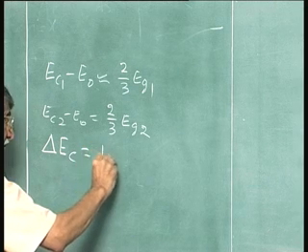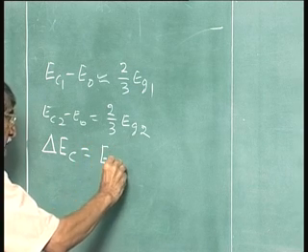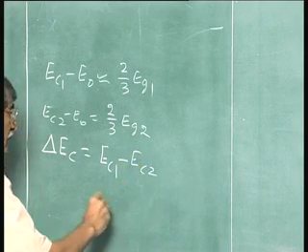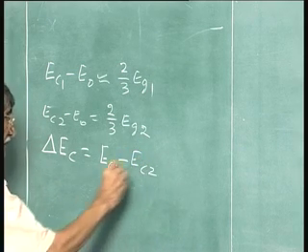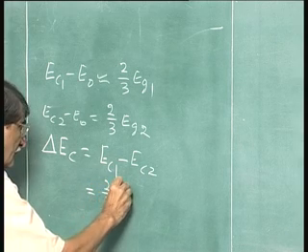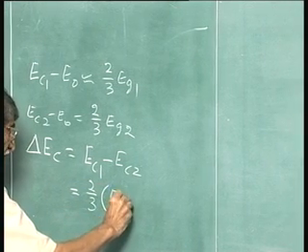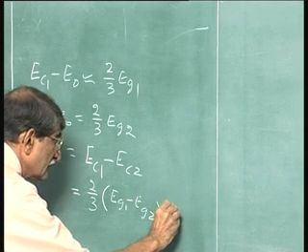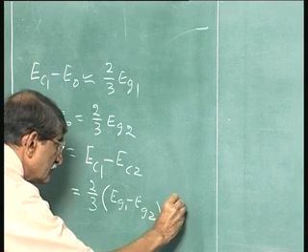Now, I just want to take a look at this particular distribution. I will try to discuss a few things now related to this diagram. This is the n plus aluminum gallium arsenide heterojunction with undoped gallium arsenide, doping concentration unintentionally doped, and depletion layer here, because charge transfer has taken place, entire band bending has taken place.